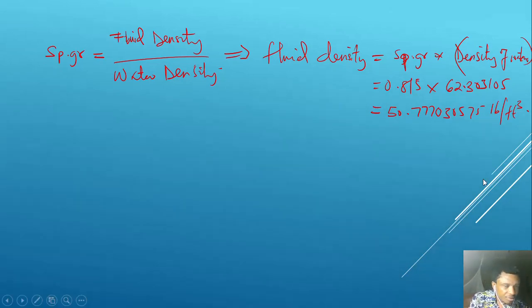Now, you know that the head loss is the same thing as friction factor times the length of the pipe divided by the internal diameter times velocity square all over 2g. Now you have the length in feet, this one is in inches.